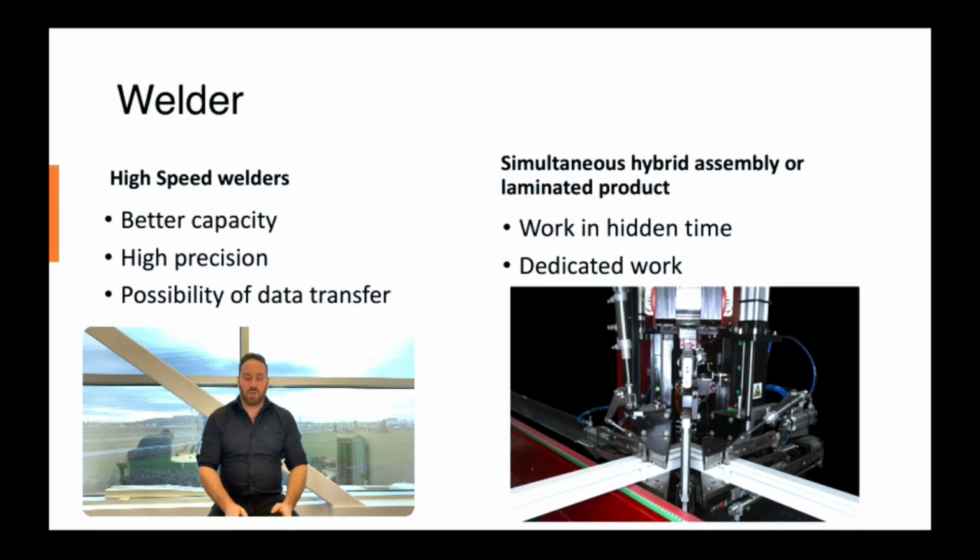You could have also, if you have a 3 light, the same system could be working, making 2 different sets of holes on each side. Just keep in mind that if you're putting this hardware between the 2 heads, you're making your minimum weld a little bit bigger. So if you're going to be using the same welder for frame and sash, I would not recommend having that installed on a welder.